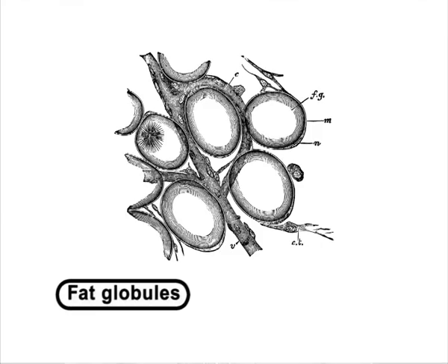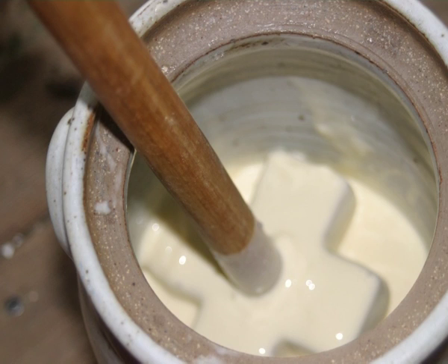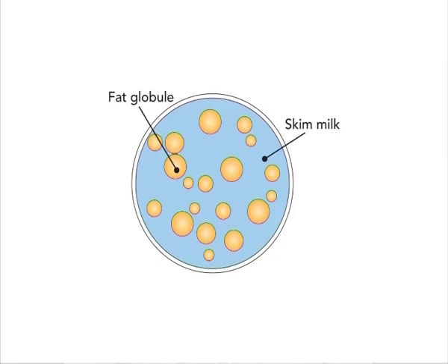Homogenization. Homogenization is the process wherein the bigger fat globules are broken down so that the fat does not rise to the top during aging period and does not churn out into butter granules during freezing process. It is a high-pressure operating equipment wherein the product is pumped through a very narrow passage such that the fat globules, which are bigger than the passage, are broken down to smaller sized globules. Once the fat is broken to smaller size, they lose the tendency to separate out from the mix and do not get churned out into butter granules during the freezing process.